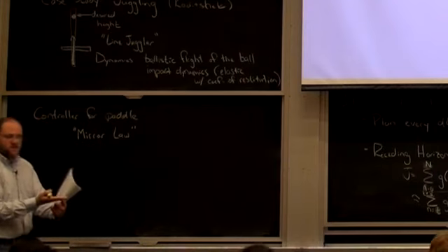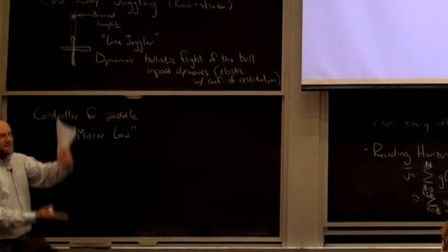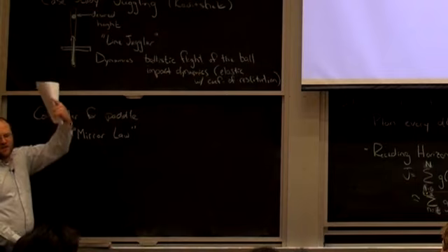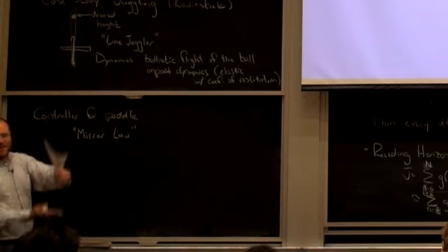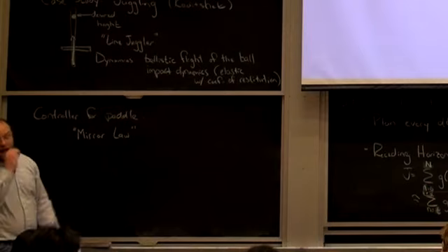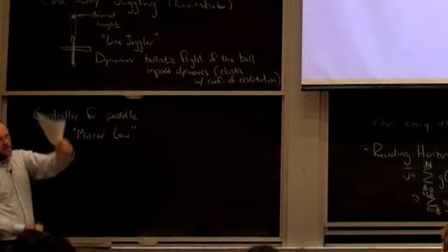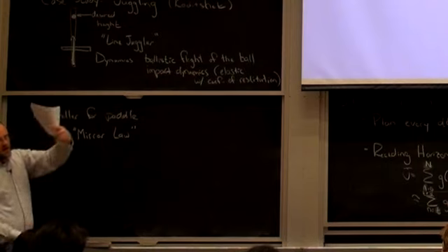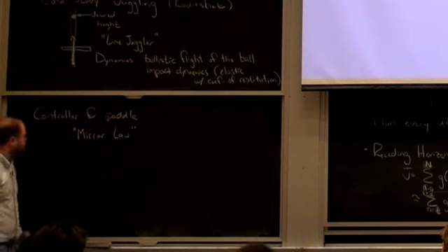Turns out if you can sense the state of the ball, and you just do a distorted mirror image of that ball, then everything gets really easy, right? Your impacts always happen at the same place, and just by changing the velocity here, you can roughly affect the impact height. So they can nominally stabilize some limit cycle with just mirroring the ball, and they add an extra term to stabilize the energy to get it to whatever height they want.